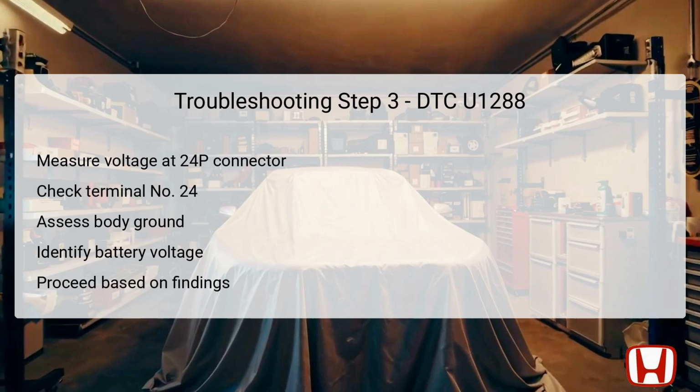A lack of voltage at this terminal suggests a disruption in the power supply, signaling a need to check for issues such as faulty wiring or a blown fuse. Accurate readings here are critical, as they will direct further troubleshooting steps to isolate the source of communication failure.